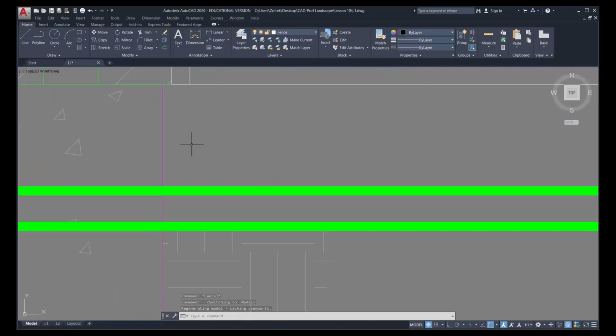And I'm going to draw the lower bracket first. So I can draw two lines. You don't have to be accurate with its length. You just need to know that it has to be at least 2.5 inches long. I got a 4-inch line in this direction. I'll draw another one in this direction. And then I'll use my offset to create all the different dimensions that I require.